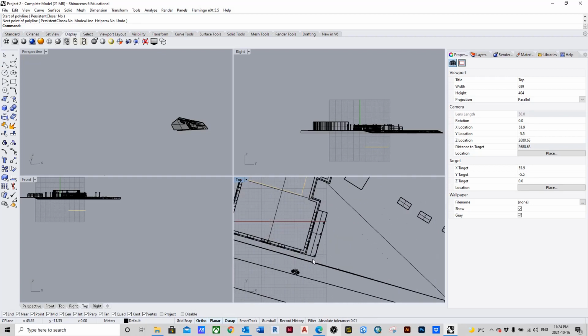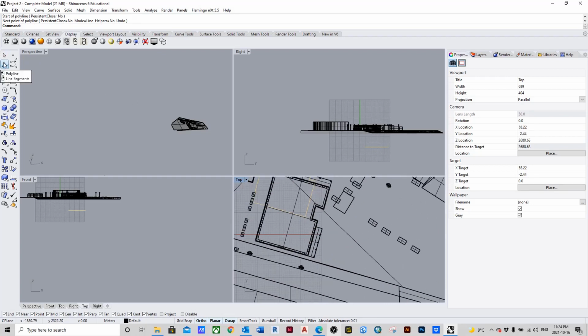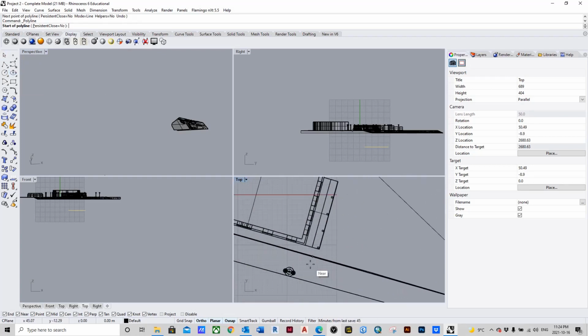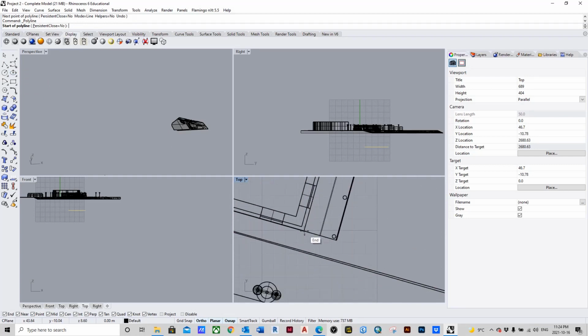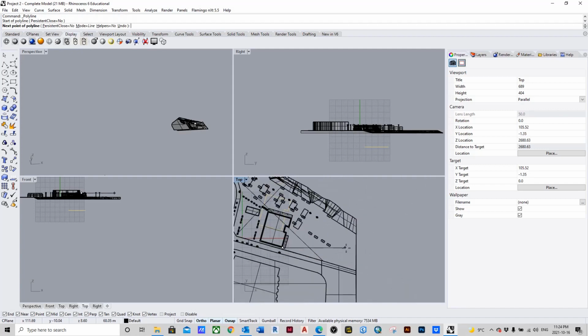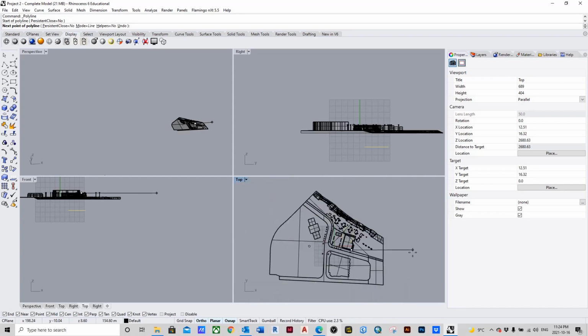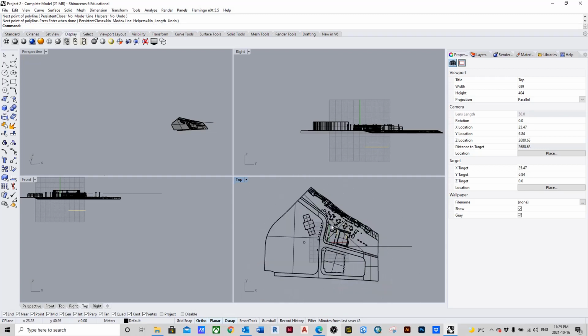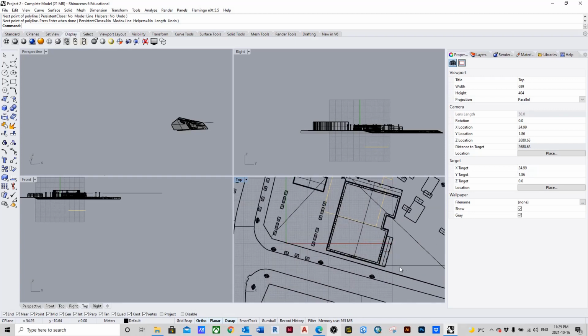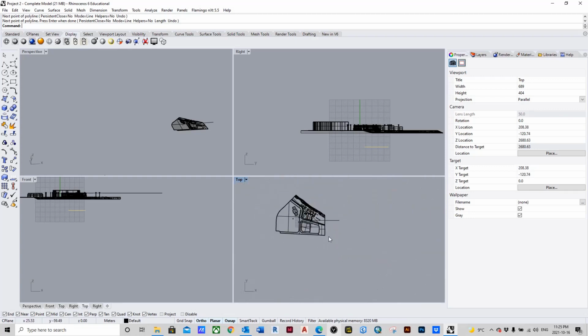So that's going to be the first step. Let's grab a polyline, left click, move over to a point on the top view. It can be really anywhere. It's just a reference ruler right now. Left click, drag a nice perpendicular line here. Left click again, hit enter to end that line. Now we're going to take this whole big mess here and rotate it so that this face is concurrent with this line here. And then we'll be ready to get started.